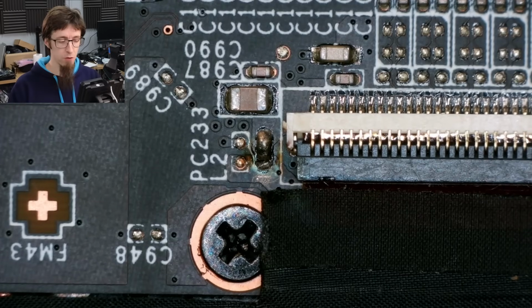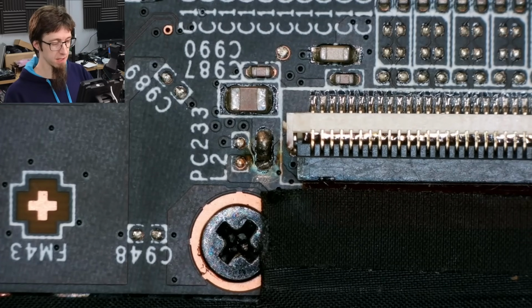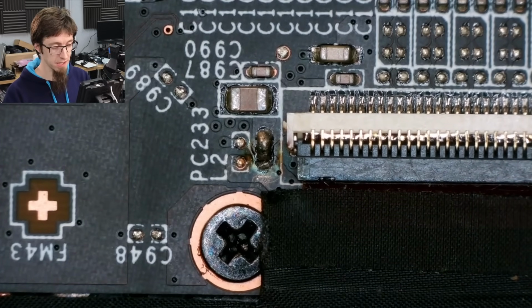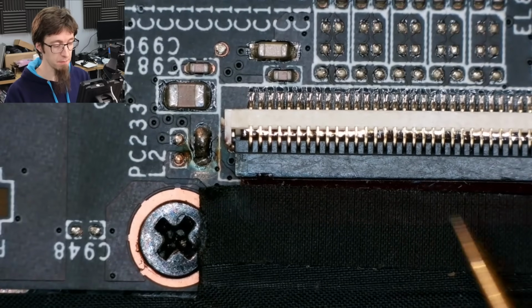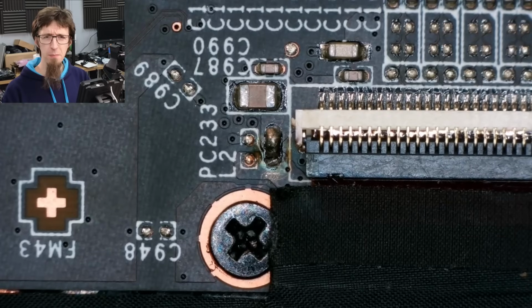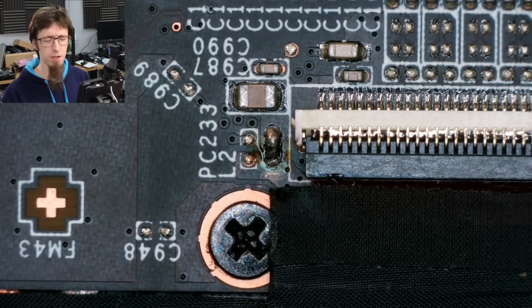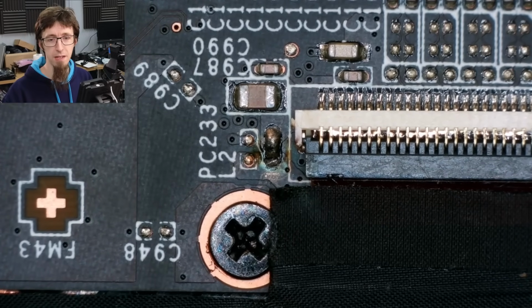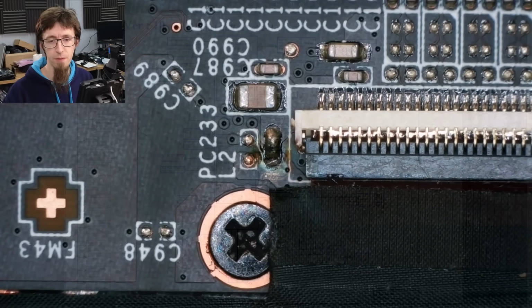So we've got a blown backlight filter inductor. So what is this doing? Well, this is the main power rail coming into the backlight of the display connector, which you can see on the right here. And it's probably a bit easier to visualize this if we have a look at the schematic for this. So this motherboard is an MS-16Q41, and through the miracle of bad caps, we have a schematic for it.